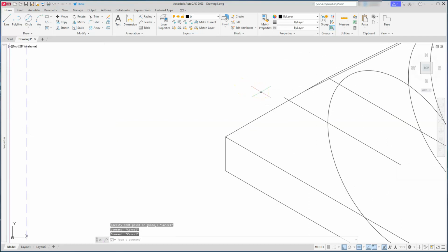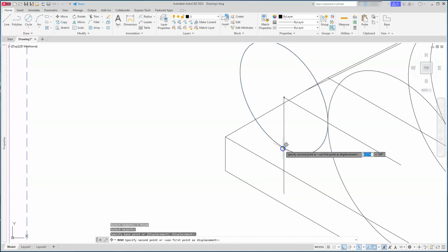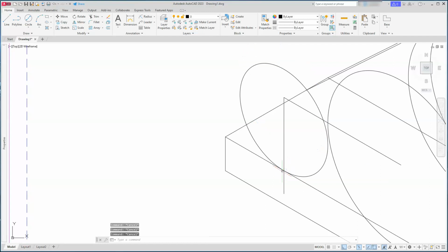I'm going to create an ISO circle, but first, before I do that, I'm going to switch to isometric left. So I'm hitting F5. EL, enter, I, enter. Select this endpoint, radius, 18, like we did before. Draw a line from that endpoint coming straight down. Move this circle from that intersection down to this intersection. Let's draw a line from that endpoint going straight down to this direction. Okay, I'll go ahead and delete all of these lines.